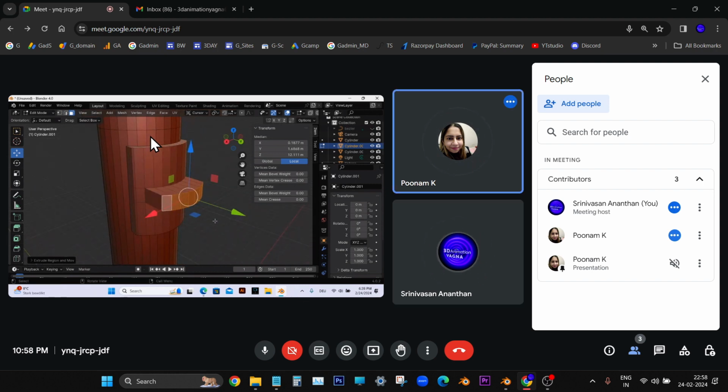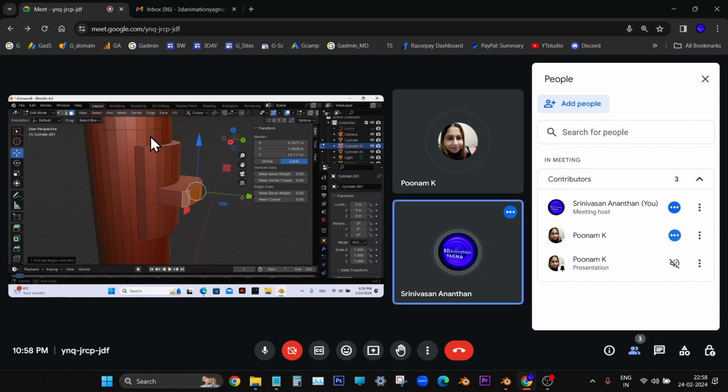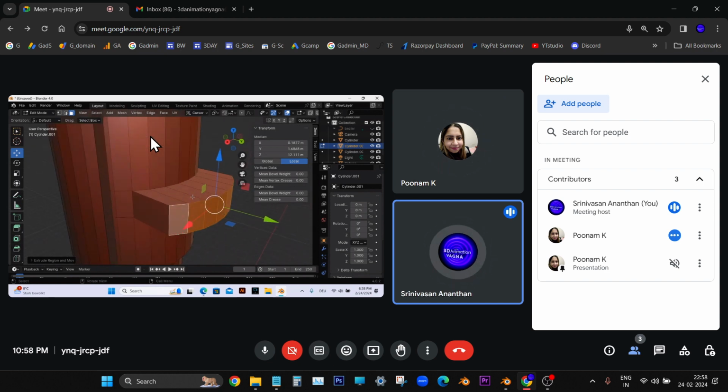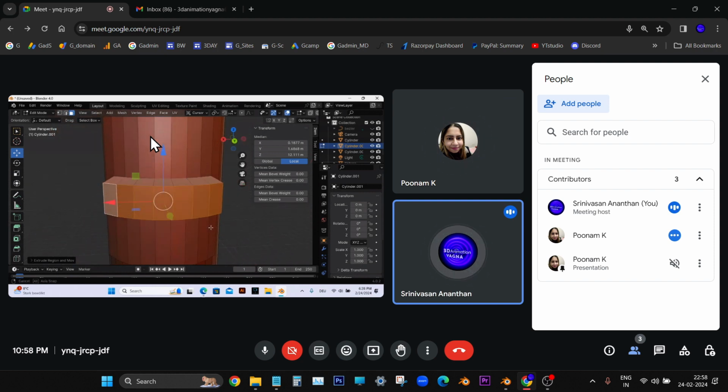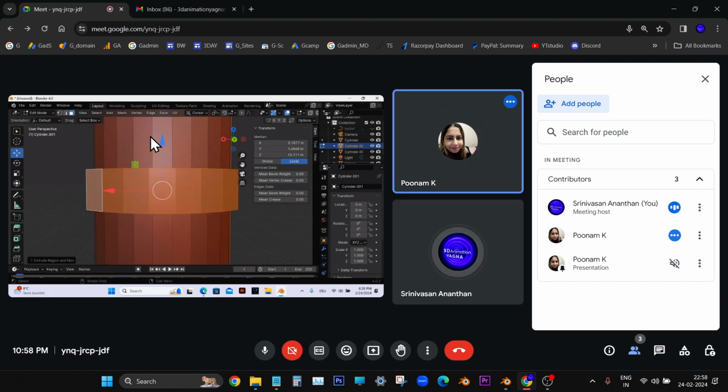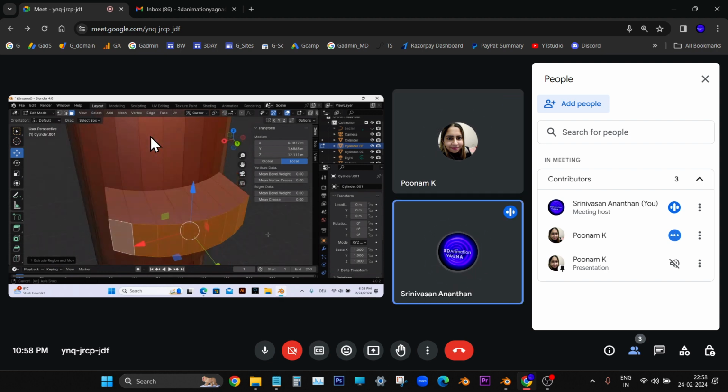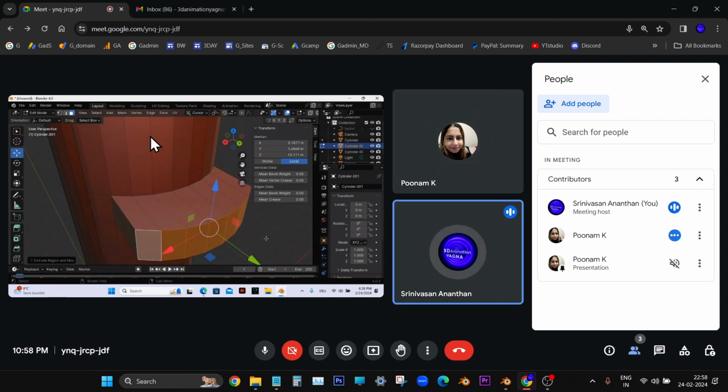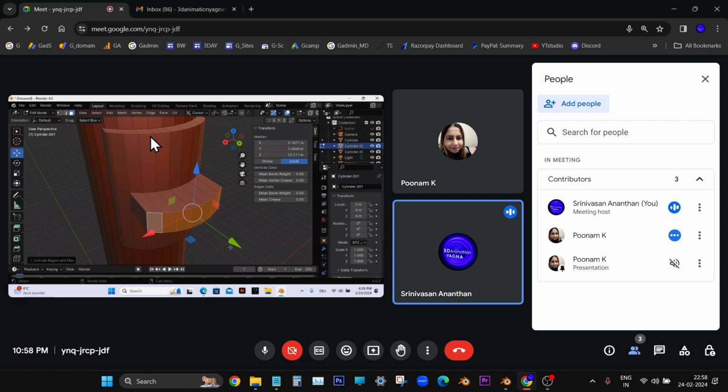Now move those faces forward, whatever you have selected. Use the green color handle and move it. In this phase you cannot. Turn the camera and see it sideways. Right. Now zoom out a little. Choose the green handle and move it forward.